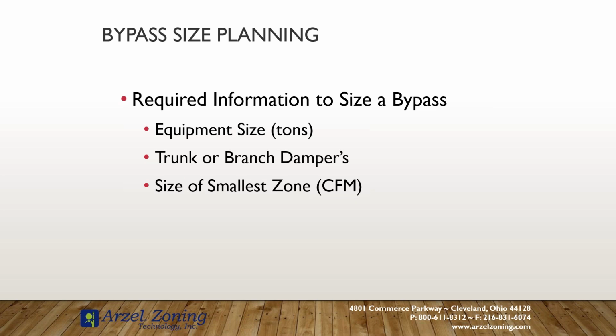So if you got 4 6-inch runs going to it, figure it 400 CFM. That's really what we're looking for. What is it designed to handle without zoning? That's your smallest zone CFM.